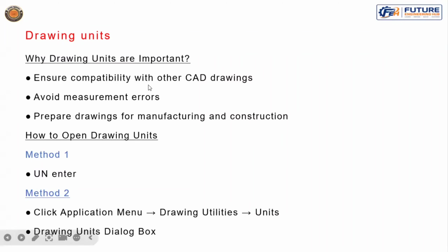Ensure compatibility with other CAD drawings. Avoid measurement error. Prepare drawing for manufacturing and construction. How to open the dialog box of drawing unit? Method 1, UN enter. Second method, click application menu, go to drawing utilities. Under utilities, units, drawing unit dialog box. Clear up here?